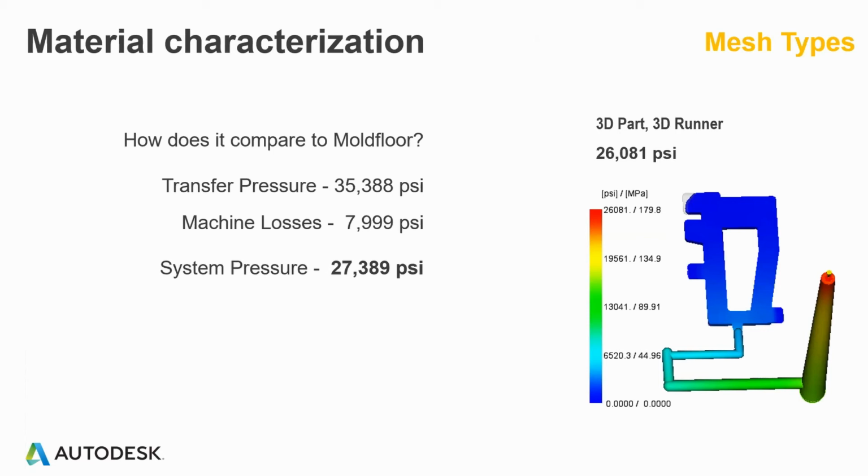The one other note I'll make, and we don't have a slide for it here, but how they take that pressure loss out of the nozzle is very important. Many machines don't purge into the air under the same conditions in which they inject into the mold. They may have purge settings, reduced velocity for safety or something. That will not give you an accurate screw conveyance and air shot pressure. So the machine needs to be set up to inject into the air under the exact same conditions, speed, pressures, everything that it would inject into the mold in order to get an accurate number there.